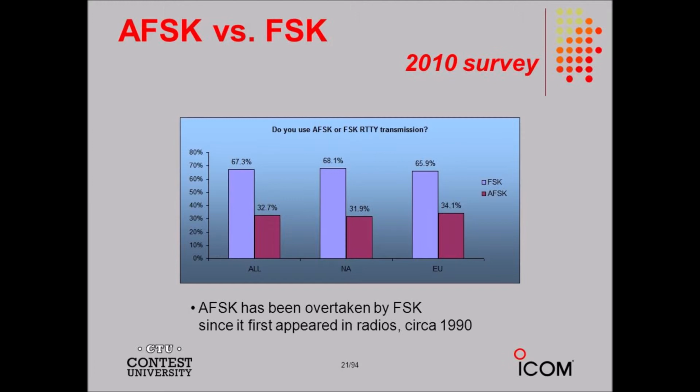In standard AM broadcasting, where music is transmitted along with voices, the AF energy is spread over a wider bandwidth, nominally 10 kHz to 20 kHz. The increased bandwidth provides for better fidelity, sound quality. Single sideband.